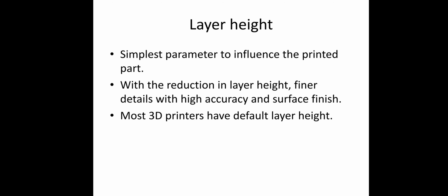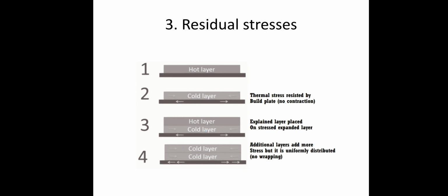Layer height is the simplest parameter to influence a printed part. With a reduction in layer height, finer details with higher accuracy and surface finish will be obtained. Most 3D printers have their default layer height.